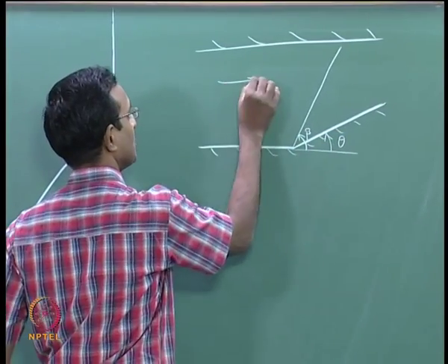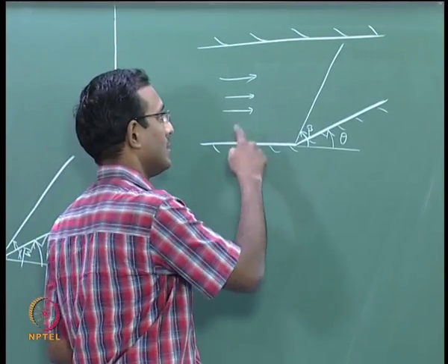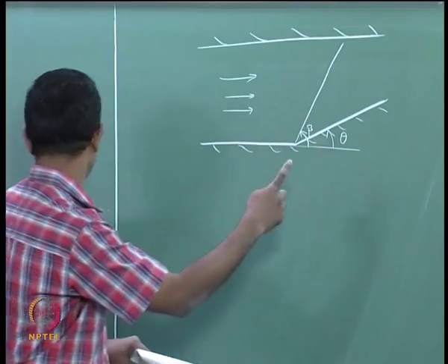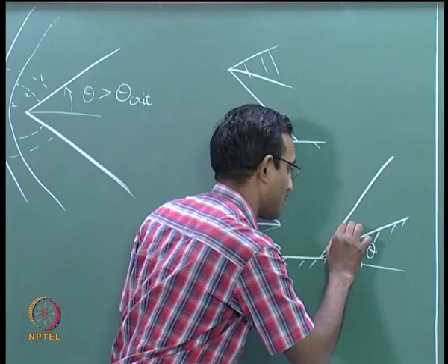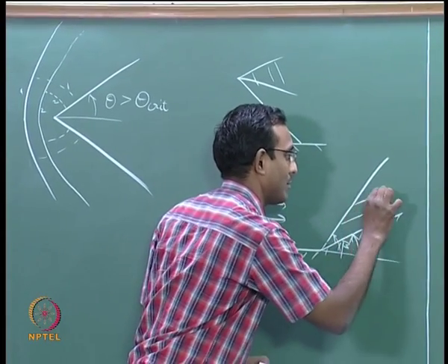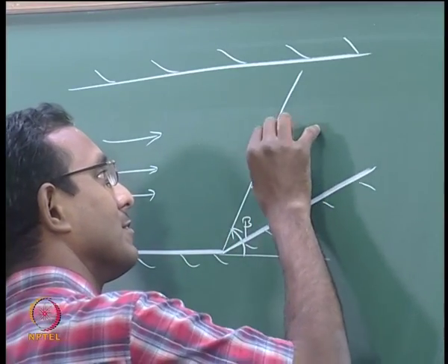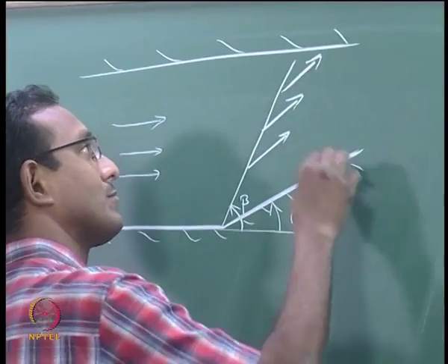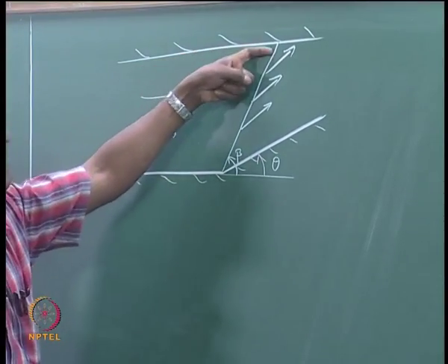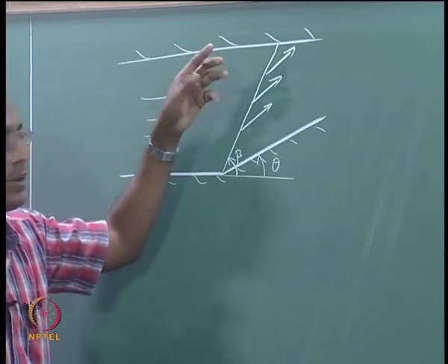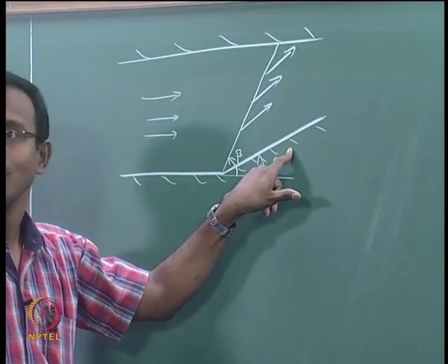Okay, and there is some supersonic flow incoming, and I am going to say this basic problem here is just the same as what we did here, exact same problem, no difference. I will just copy stuff. The streamline here will be parallel to this wall. So, I will just go and copy this there, I will just put lines like this. Up to the last streamline where the shock goes and touches the wall, all the streamlines want to turn like this, parallel to this wall.